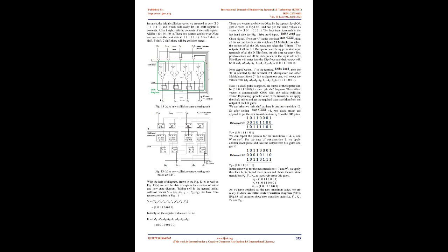And this vector is loaded in the shift register if we set equals 0 and apply a positive edge trigger clock pulse. The register is then shifted towards right 1 bit. We know a 1-bit shift represents an increase in the latency by 1. Similarly, a 2-bit shift corresponds to an increase in the latency by 2 and so forth.